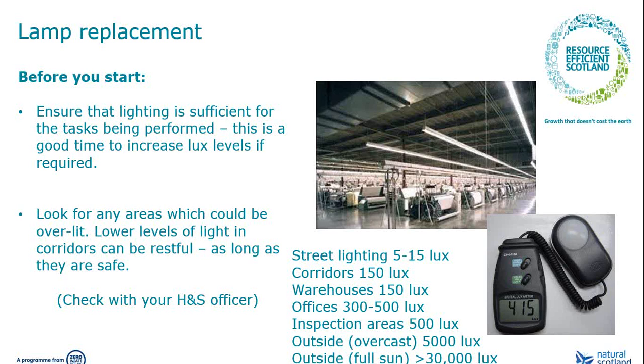So what are the things you should think about before you start replacing lights? Well, it's well worth doing a little bit of a lighting survey just to check that lighting levels are sufficient for your current space, the current use. And in the picture at the bottom right there is a little lux meter, and you can walk around. In winter evenings is a great time when there's no natural light coming in, but take your readings when you're depending just on artificial light and see what lux levels are there at the moment.